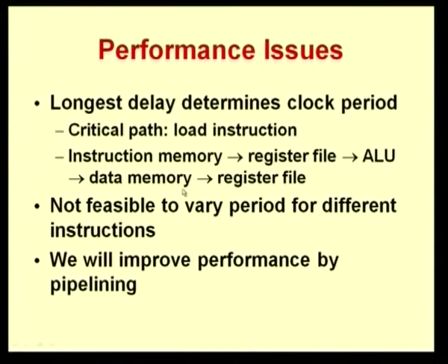Now, there are other instructions which may take a little less time, but normally it is not feasible to vary the clock period for different instructions. So, we will fix it for the largest instruction, and that would be the clock period that we would fix.